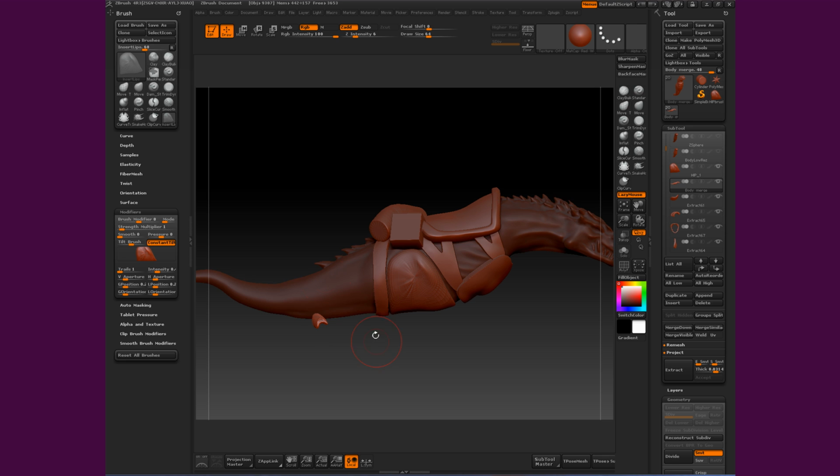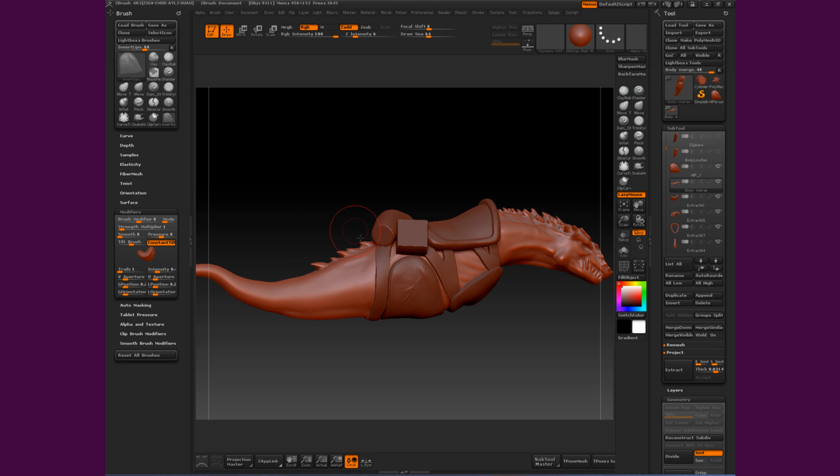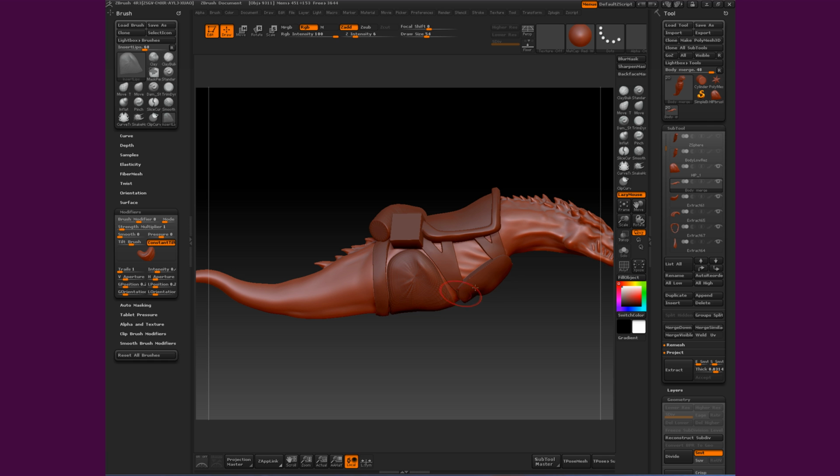So now I've already clicked on here, it's going to mask off. We want to undo that. So now that I have this selected, we have to orient it so that it matches up with the original hip location. Now this is what you'd have to do under normal circumstances. So I'm going to hit transparent just so these pieces are transparent and I can align them. You hold Alt and then click on the surface of what you want to do the extraction from.